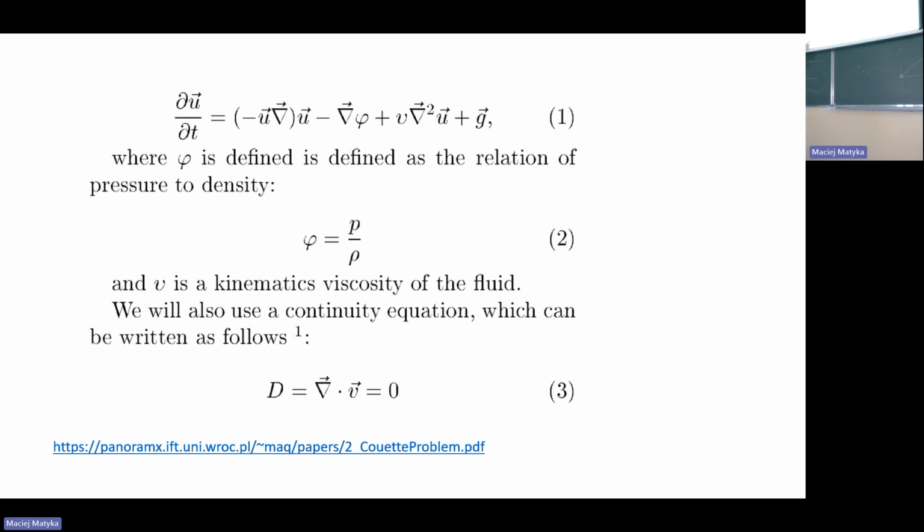It's kind of like Newton's second law, because on the left hand side you have acceleration. It's a partial differential operator which takes the derivative of the velocity field, so it's like taking a derivative at each of these points in space. On the right hand side all those terms are forces, divided by mass, of course. So it's like forces acting on each individual element of the flow.